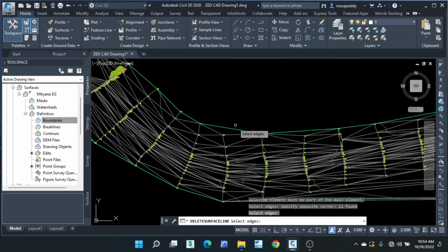Remember, when you generate your surface, it's going to map out including that area and show it as a flat surface, yet that surface's elevation is unknown. So you can just create a border that is now inwards, or you create a break line. You get? So those are the differences between the boundary and the border. So what is limiting here? Our end point of our surface is a border, and then there is a boundary.